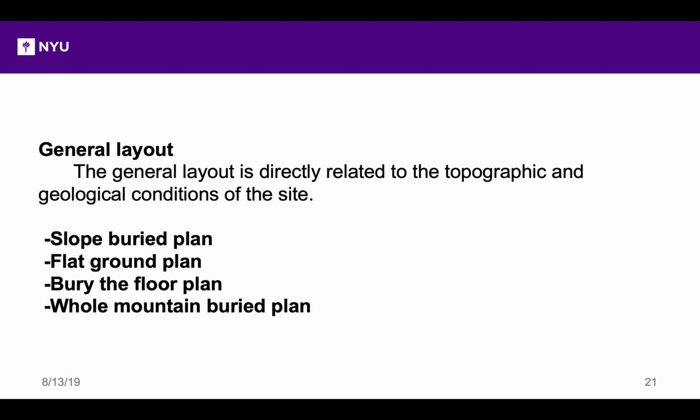We have four schemes. First is the slope barrier plan. The underground workshop is arranged in the mountain. The ground workshop is arranged on the platform outside the slope, and the underground workshop and the ground workshop are arranged on the same elevation. The secondary circulation cooling system is adopted, and the cooling tower is designed as a single tower. When multiple units are arranged, each unit shall be arranged separately, while public facilities, external traffic, and anti-seepage curtains between units may be shared.